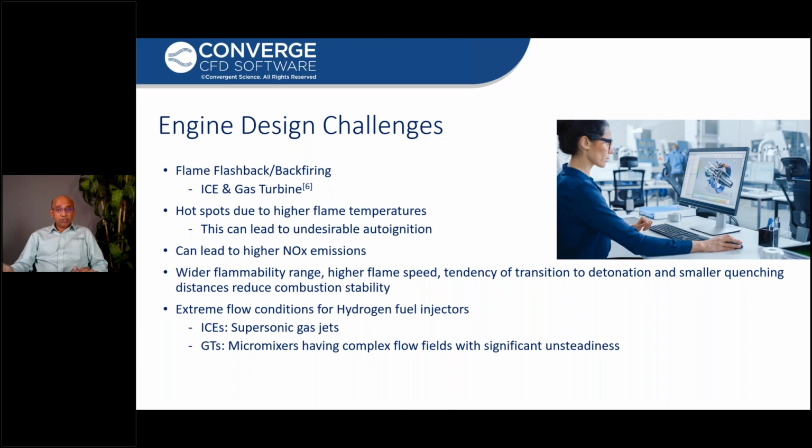Another issue is combustion stability. These combustion stability issues can arise from the wide flammability range of hydrogen, higher flame speeds, a tendency to transition to detonation quickly, and smaller quenching distances of hydrogen.